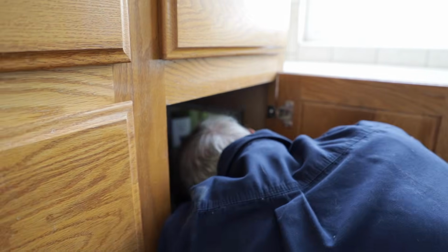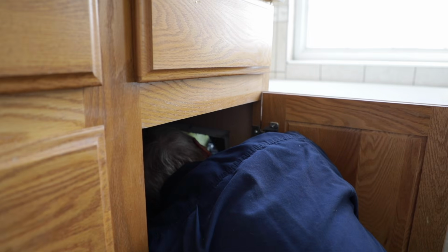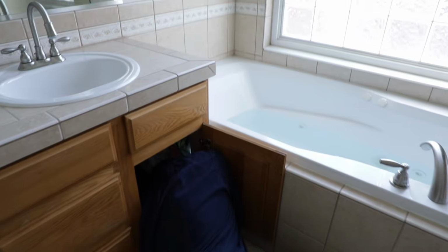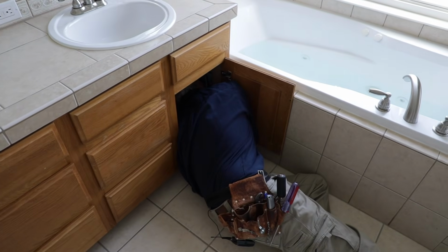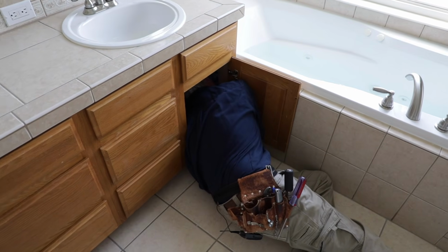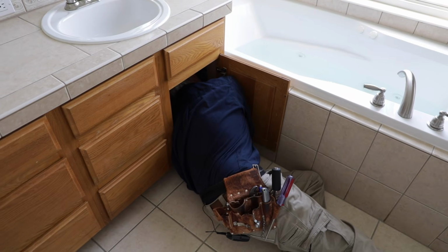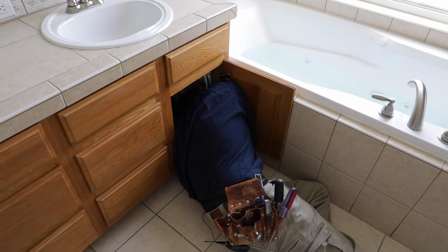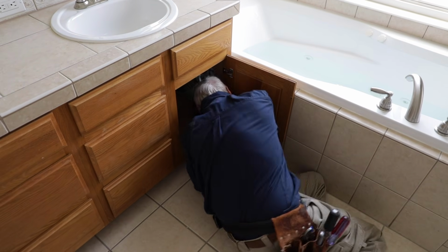I'm going to take a look at the pump on this one, which is hiding back in here. They have it bonded. There's a lug on the pump for a grounding conductor, and that is attached, which we want to see. It's a little hard to see that on this one. And then I'm going to look to see if there's any evidence of leakage, which is hard to see on this particular one.